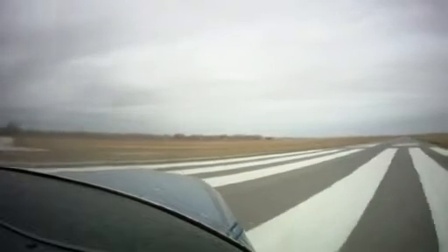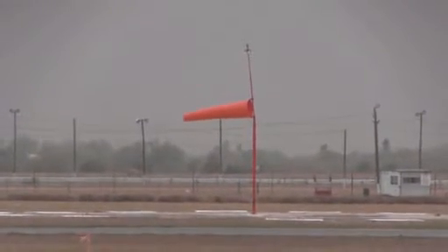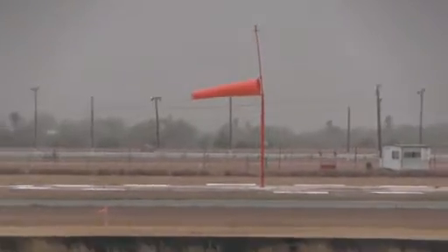As we taxi onto the runway, it is essential that the windsock be checked so the crosswind condition may be recognized and anticipated. With this in mind, full aileron should be held into the wind as we start our takeoff roll. This crosswind correction should be held while the airplane is accelerating on the runway until the ailerons start becoming more effective.